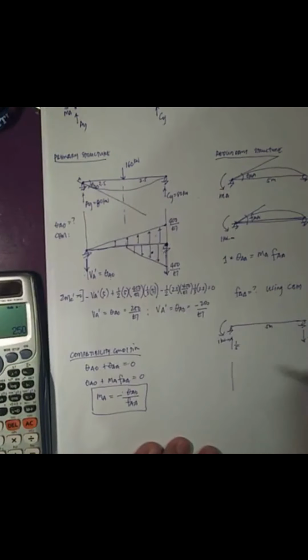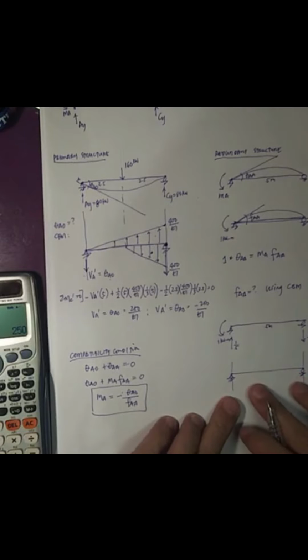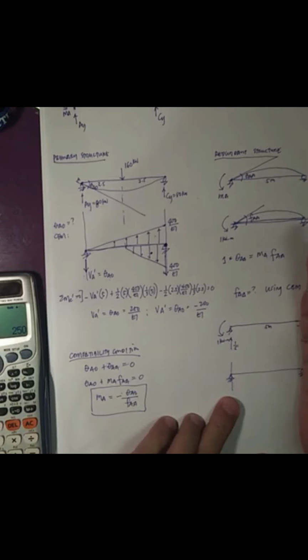So what would be the conjugate beam? Hinge and roller, so for the conjugate beam it would be the same. Then for this case, I'll draw the moment diagram by parts. If I take reference here, what I get is 1/5 times 5.